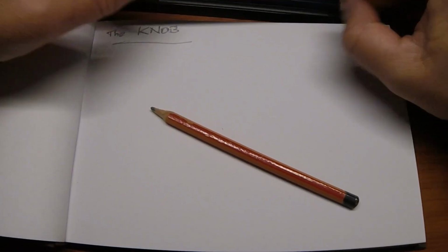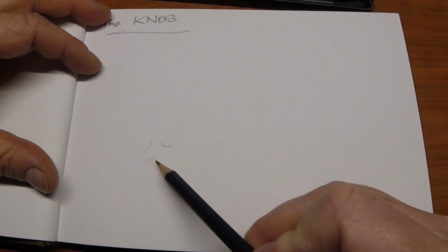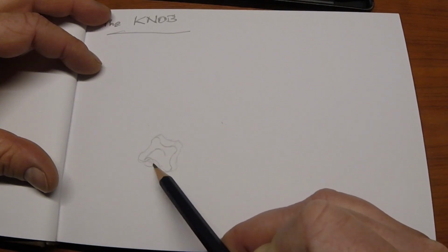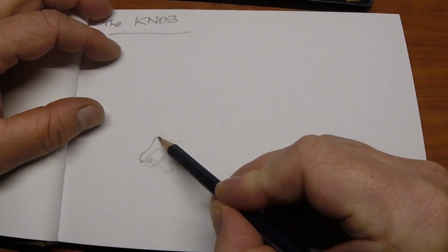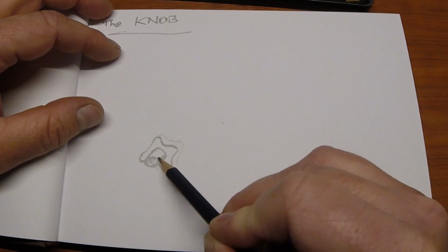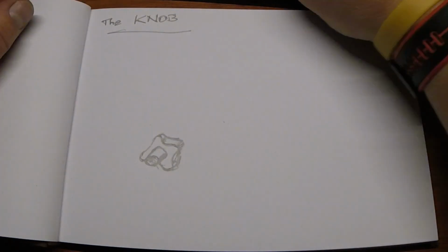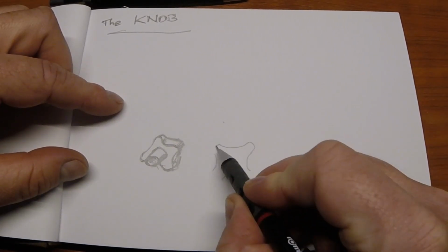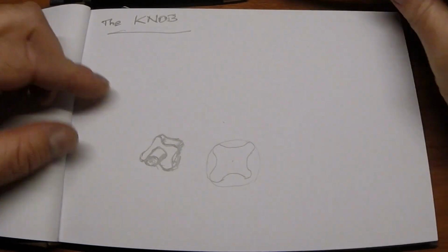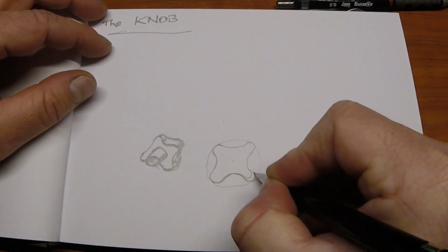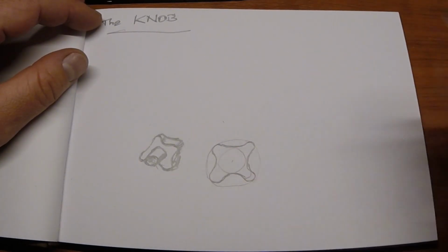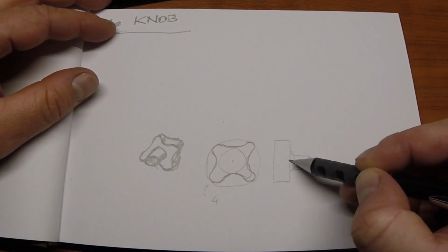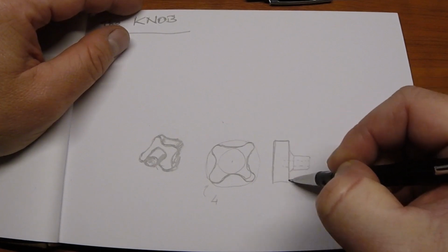The knob I will design will consist of the part where you grab it with your fingers, and a shaft where you put a screw later on. And now let me draw the views from the top. You can see there is a number of wings of this nut, and a side view where you can see the shaft and the insert in the shaft, the hole for a screw later on.